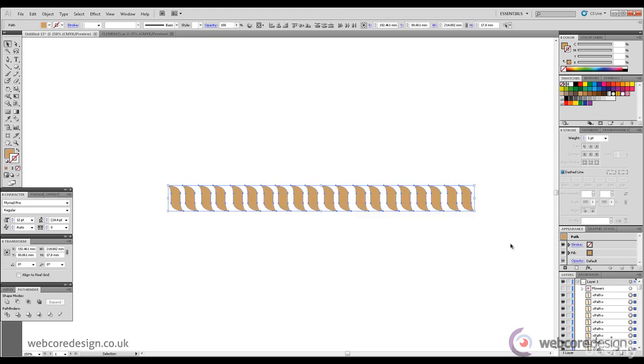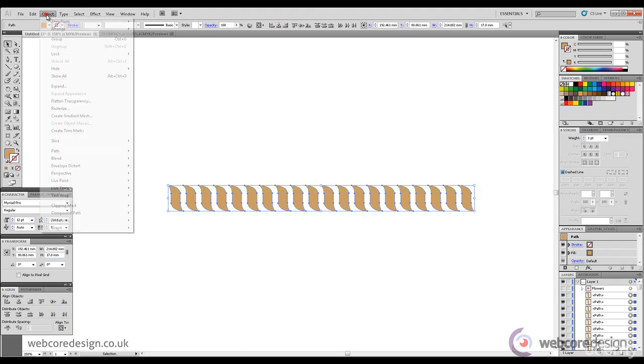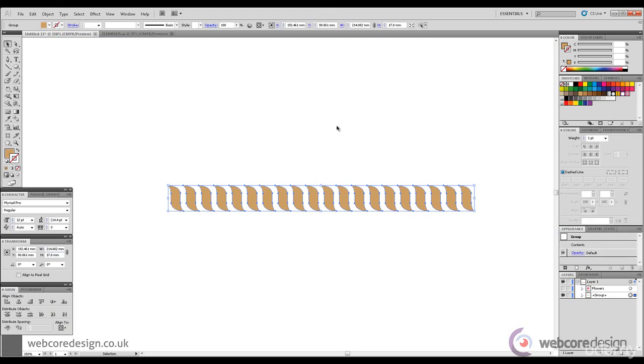And we highlight all, and just to make sure that there's equal spacing between each shape, I go to Align and I click this button, Horizontal Distribute Left. So this gives equal spacing between all shapes. And I'm going to go to Object and Group to group those shapes together. Now, as you might see, this is a kind of rope formation with all those shapes together.